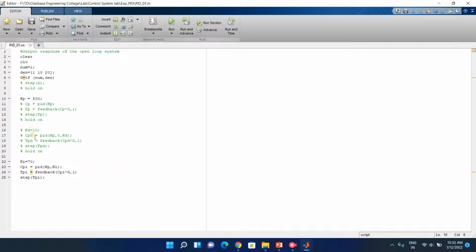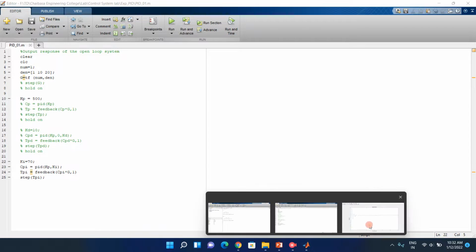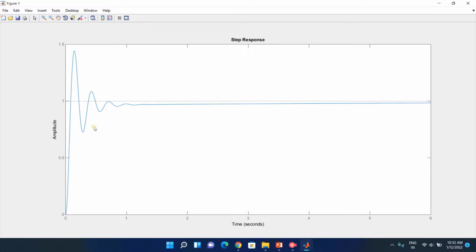Okay, so that is why we will use 30 for Ki, but once we use Kd, since 500 we can use because it will damp it, so there is no problem. But if you don't increase the value of Ki, what will happen? See, for 500 value the error was not 0, so Ki, that gain of the integral controller has to be high also, otherwise it will not be able to damp. It will not be able to make the steady state error 0.